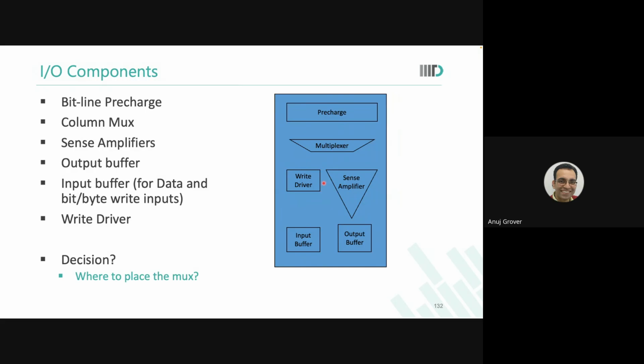But it is needed. An interesting thing is, right now also you have to decide where to place the mux. Should the mux be placed before the sense amplifier, or after the sense amplifier? Where should the write driver be? Should it be after the MUX or before the MUX? It depends on the requirement.